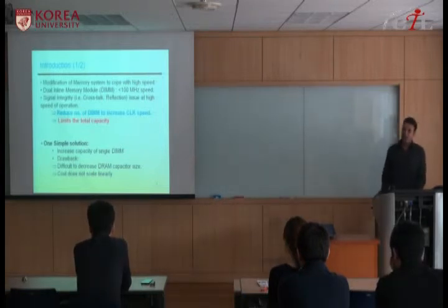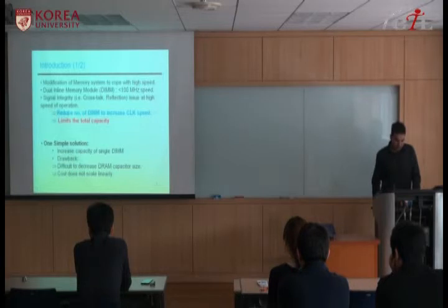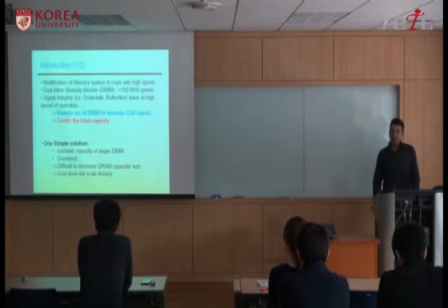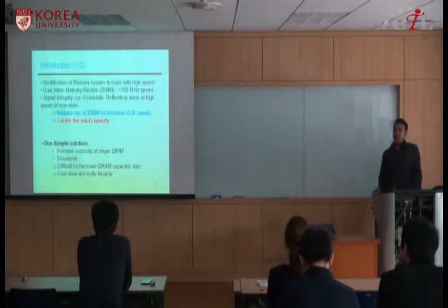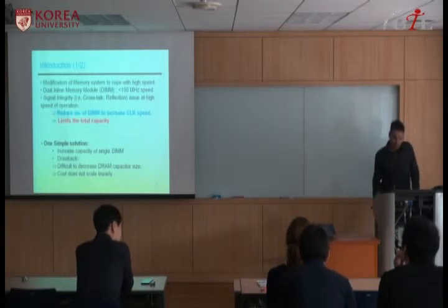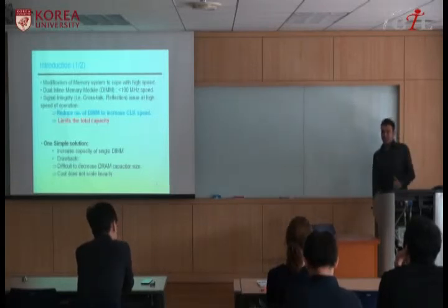What do you mean by DIMM? What is DIMM? Dual inline memory module. Yeah, I know DIMMs, right? Okay, reduce the number of DIMMs. That means the number of DIMM slots. Usually in a PC, there are 4 slots. Yeah, 4 slots. Okay, so what you mean is, suppose my PC supports 100 megahertz with 4 DIMMs, but I need, say, 400 megahertz. Then remove 3 and use one.